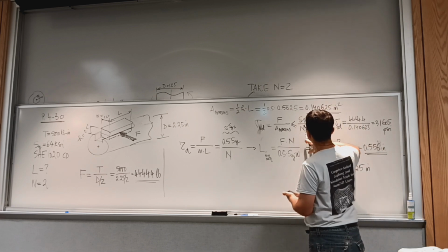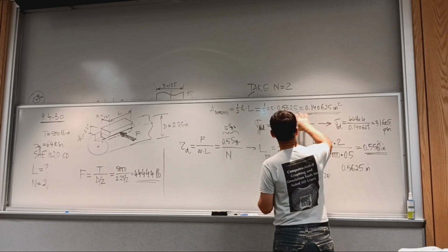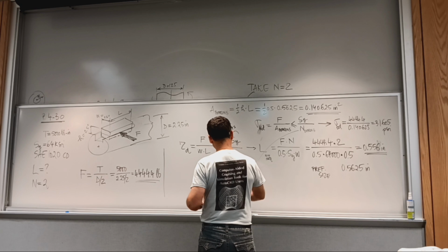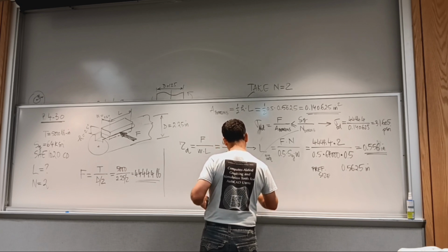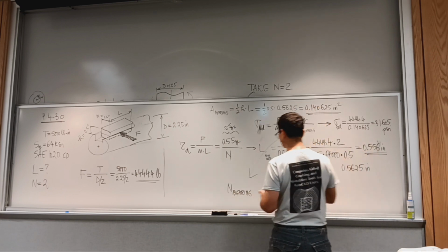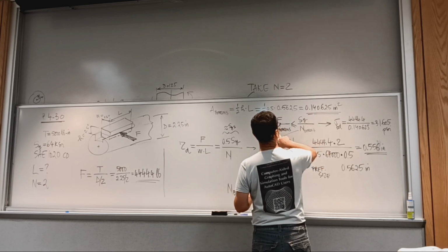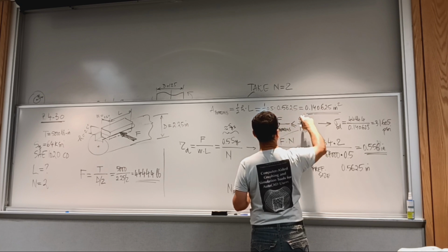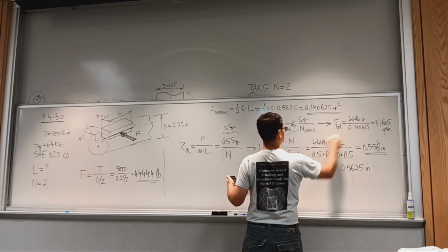And I can now calculate the limit bearing stress with a design factor of 2, or calculate the design factor. And they should be equal. If I kept the calculated length, we'd get a number that is less than 2. So the design factor equals SY over sigma BD.